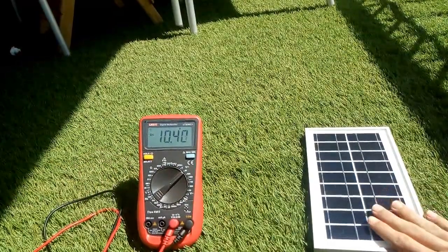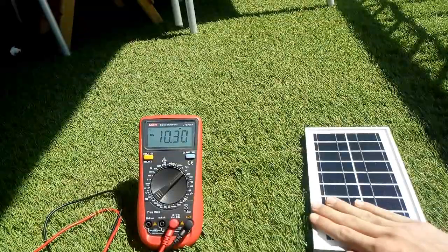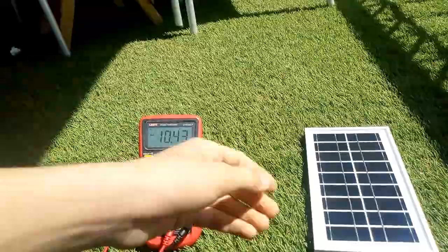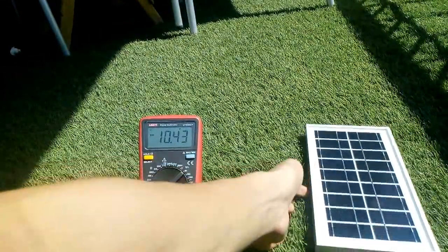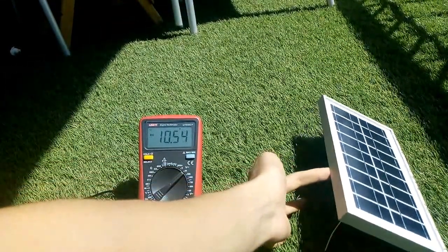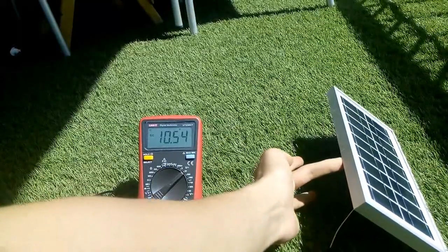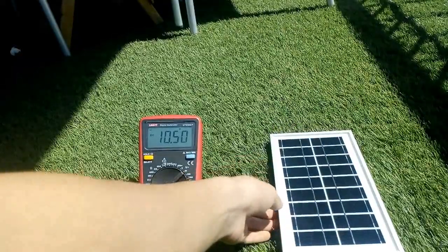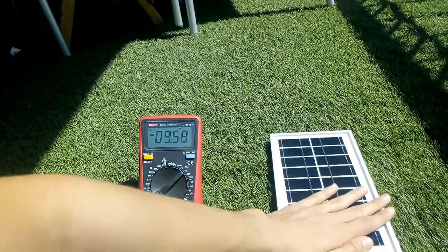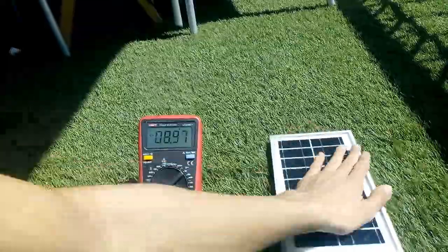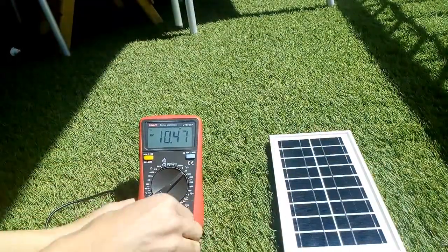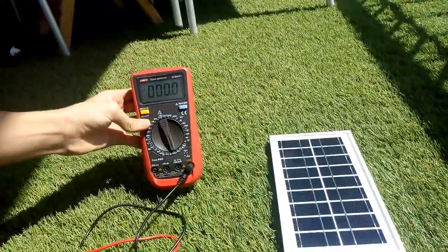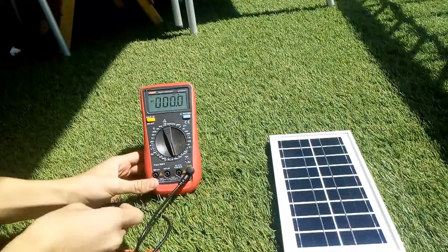In order to get enough power from the solar panel, you should never cover any cell or any part of the solar cell or solar panel, because this will affect the voltage. Also, the angle affects the voltage because it's now, for example, at an angle of 45 degrees and has an output voltage of 10.54, and now standing still, it has an output voltage of around 10.46. I will now put my multimeter in current measuring mode to measure the maximum current the solar cell can provide.